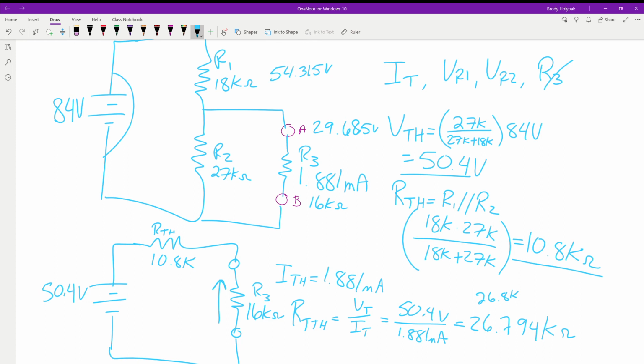So the last step we need to solve for is the current. Again, we could do this one of 2 ways. Where is our total current in this circuit? R1. Because it's directly in series with the source. So the current of R1 is our I total. We have the voltage, we have the resistance, we can solve for it. So I total is equal to IR1.